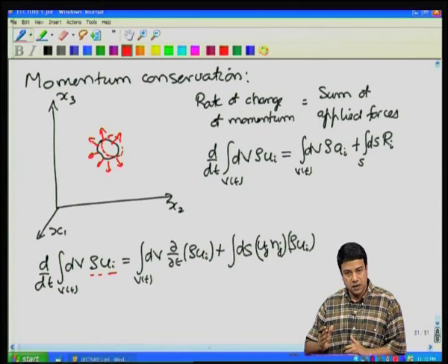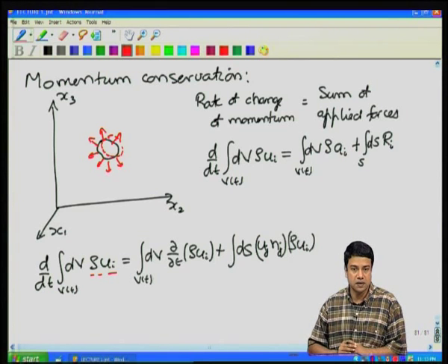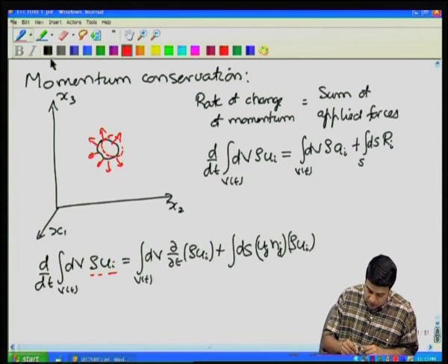So, on the second term, surface integral of n dotted with something. That thing is now a second order tensor, because n is now dotted with rho ui uj. So, it is dotted with a second order tensor. So, integral of n dot something is equal to the integral over the volume of the divergence of that same thing. It does not matter whether it is a vector or a tensor. I can always take the divergence of a second, third order tensor, as I had shown you in the previous lectures. So, this just becomes equal to